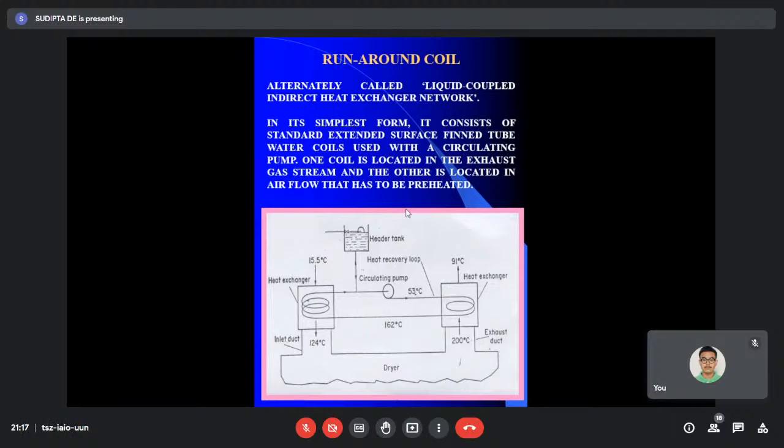The device is very simple: you need a pump and two heat exchanging surfaces located in two streams with different temperatures, and effectively at least some heat can be recovered, which reduces the required cooling load for the refrigeration process of the air conditioning where cooling is required.